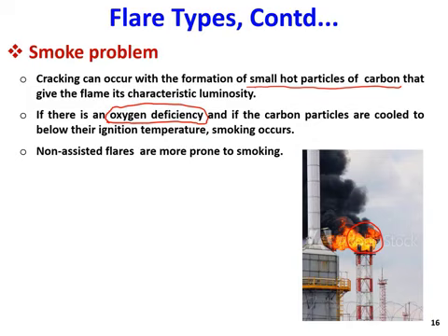Because of the oxygen deficiency, those hot, small carbon particles cannot be combusted completely at lower temperature, and they produce that smoke. Non-assisted flares, the flares where we don't use any air, steam, or ignition agent, are more prone to smoke. Okay.